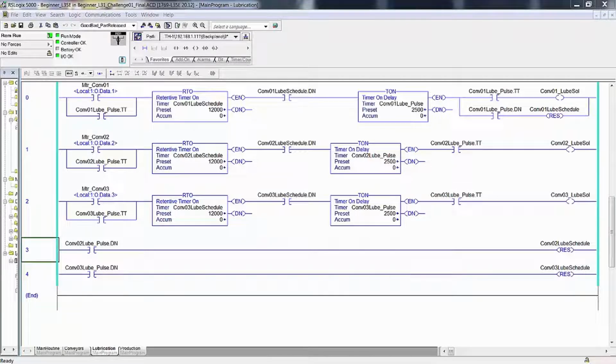When the conveyor has moved the part forward, it eventually clears the photo eye and the photo eye reverts to the off state. This means that you have to flip the switch or hold down the push button that represents the photo eye. You're going to have to turn it on and leave it on until you see the motor running. Then you can flip it back off or release the push button.